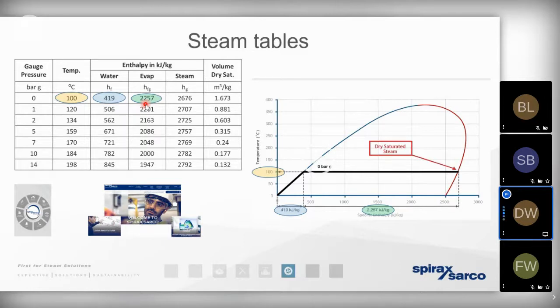It also means that if we've got a significant amount of condensate held back in the distribution pipework, we're at risk of a little bit of corrosion of the pipework and the other ancillaries as well. That's going to require an ongoing burden of maintenance. And it also means that we may get specks of rust or corrosion entrained within the steam.